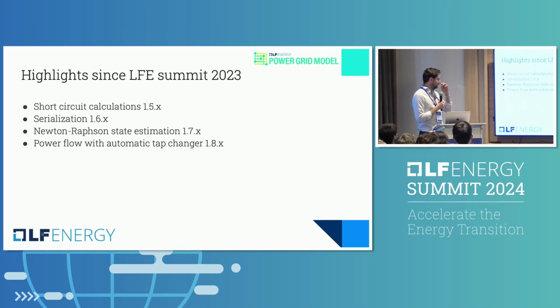And then the newest release is power flow with automatic tap changer. So you can do power flow calculations and find the corresponding tap settings to your voltage set points.